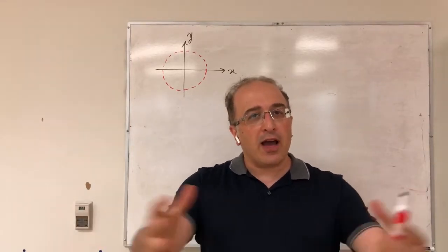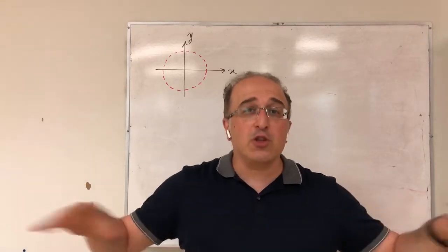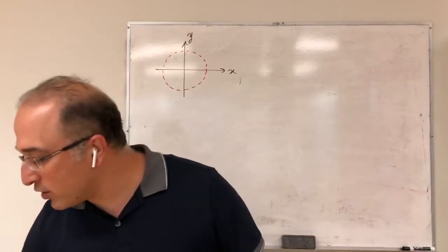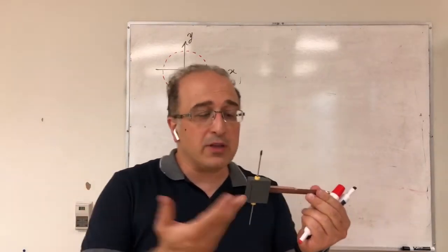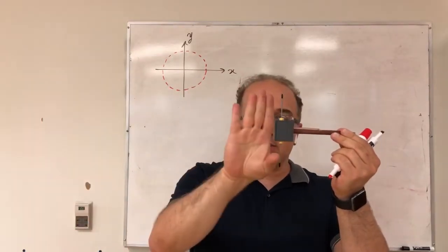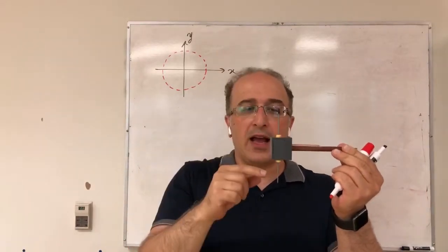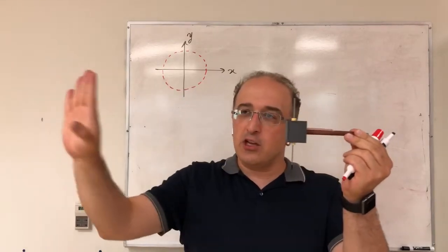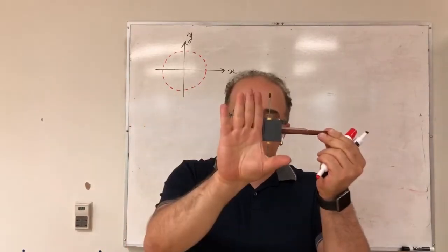You might want to have this type of pattern in one plane to make sure that you have good coverage. So that would be one cut. And then the other cut that's sometimes very important, for example, for this specific antenna, would be a cut in this one. So if this is my z-axis, and let's assume this is my x-axis in this direction, so essentially you want to know the pattern in the zx plane. So this would be the cut that I want to know.